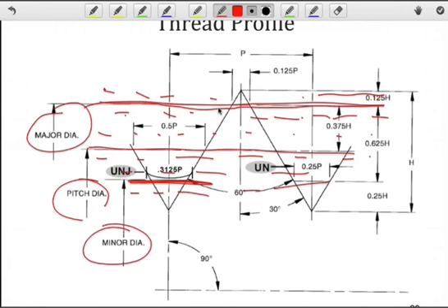And that's why it's problematic if you see a thread feature that is being controlled with a geometric tolerance and you use a material condition such as M. Question is, and a lot of confusion, which value, because you can only use one number for your tolerance zone, which tolerance value do I use?